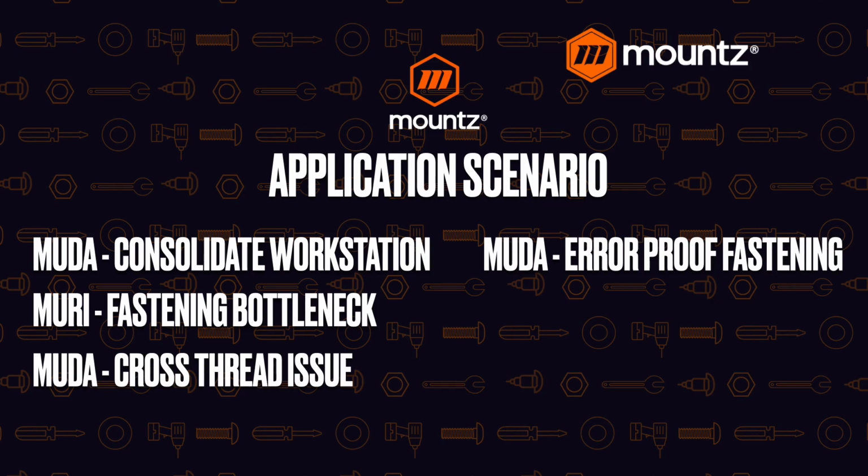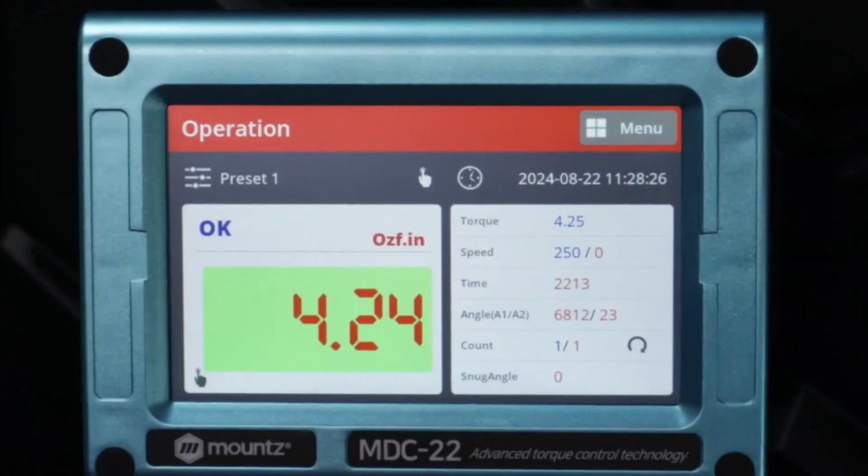All right, the next is we want to look at how we can actually error-proof the fastening. If we did have a cross-thread event and the operator really wasn't paying attention, what would happen is the fastener would bind up, the tool would hit torque, and the operator may just continue to go on. Because the tool shut off, it hit torque, and they just keep going about their operation. But in essence, that fastener is not providing any type of clamp force for us within that operation. So how can we do that here?